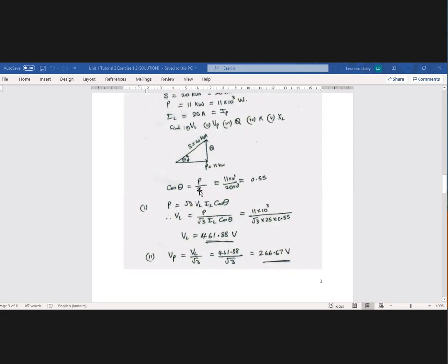or what you appear to put in. That's why it's called apparent power, because you would think that this is what you should be getting out, but you're actually getting out less. All right. So we work out cos theta. We know that the power is root 3 VL IL cos theta. So from that we can find VL. Well, that's one other thing that we're supposed to find.